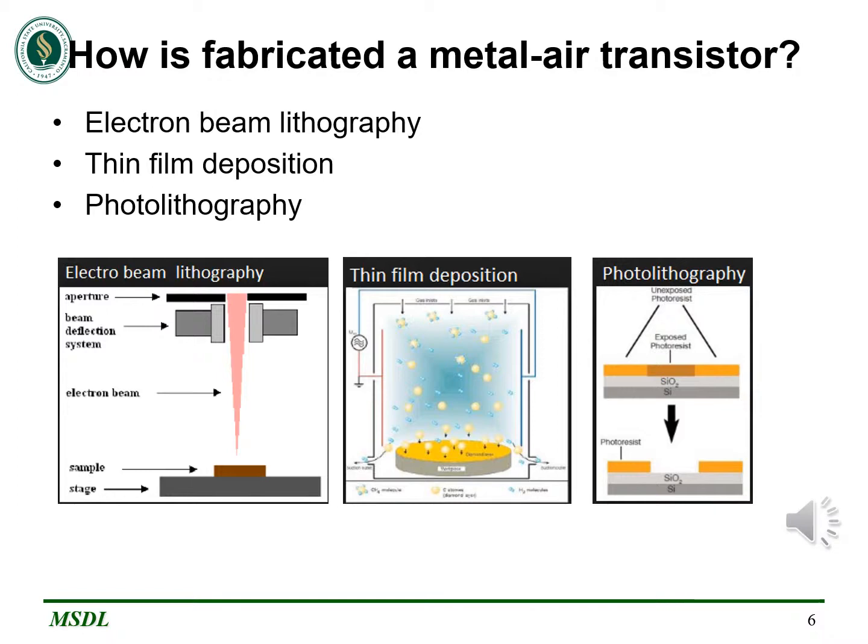The resulting thickness of the bilayer resist was 120 nanometers. Next, a 10 nanometer thick conductive layer of chromium was deposited by electron beam evaporation to avoid surface charging during electron beam lithography.